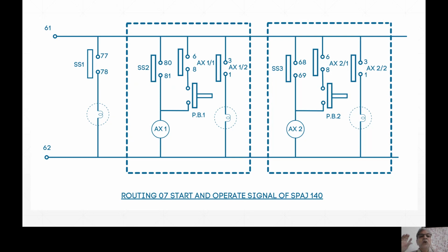But yet we are teaching that old disk type relay. It has got a coil and 7 tappings are taken out, 50 to 200% in 7 equal steps. And then how we are controlling is the time multiplier setting. Time multiplier setting is controlled by a backstop. You can bring the backstop near or away, but that backstop is not there, my friend, now.